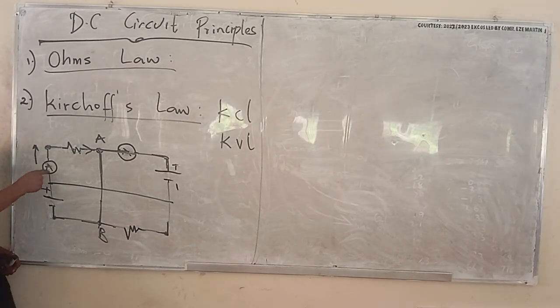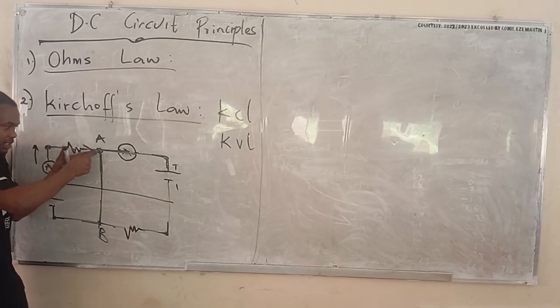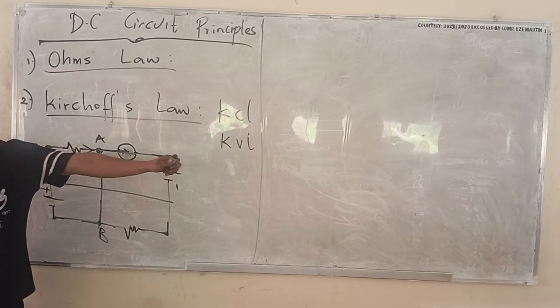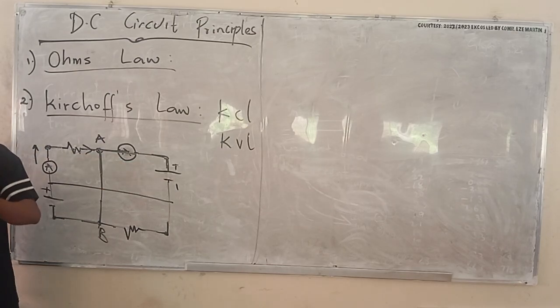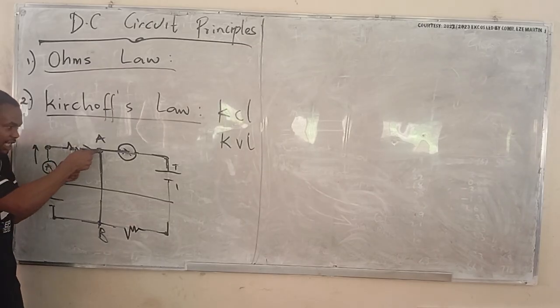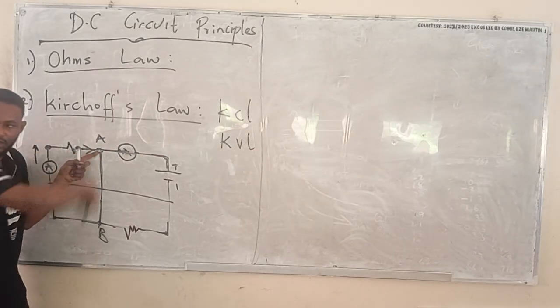This principle is saying that whatever current is coming from here and flowing into this, that is the junction, that point that has three ways, just notice that that point is linking 3 things, the current it will receive, the current coming inside it, is equal to the current it's giving out.